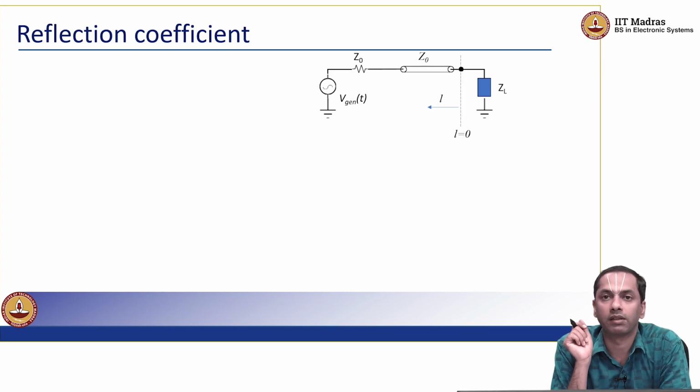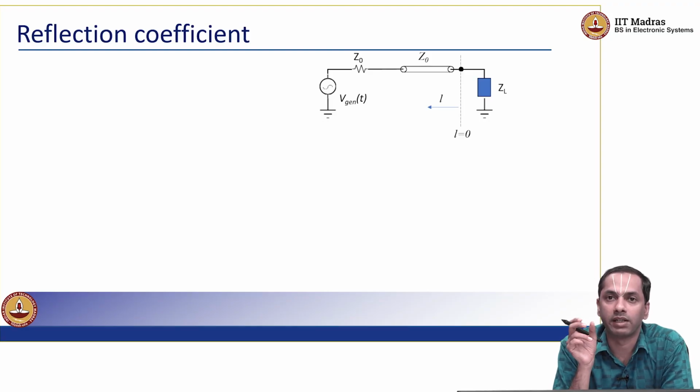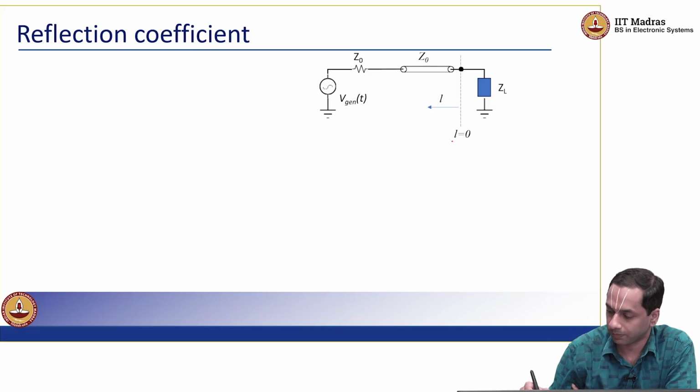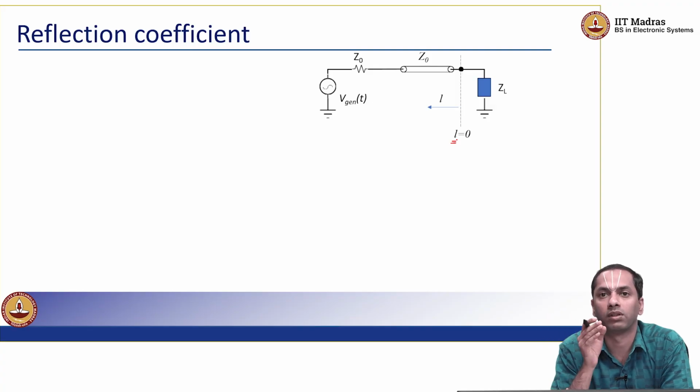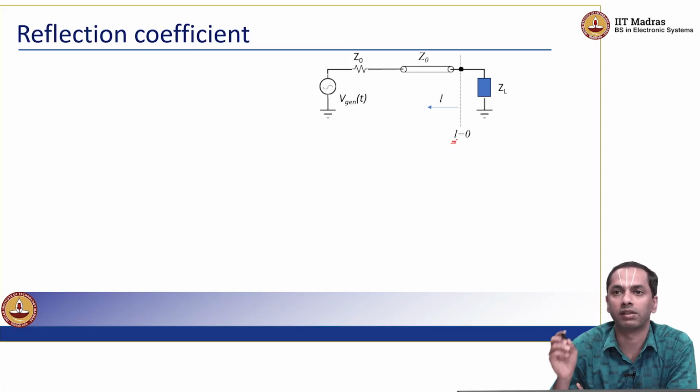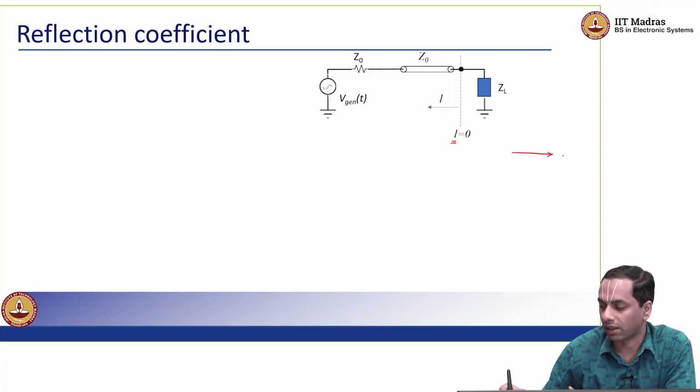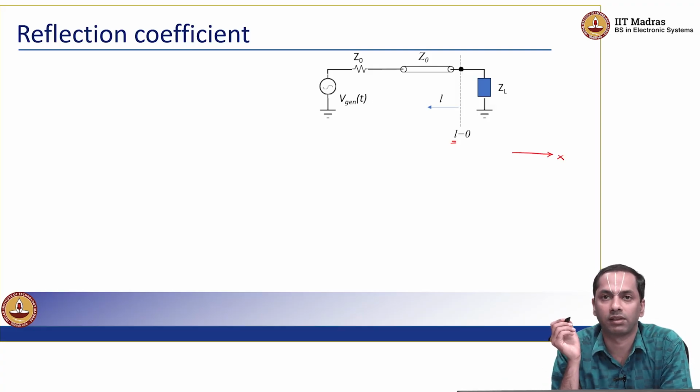So this is where I think the textbook that we are referring to, by Professor Shevgaonkar, does a small change in variable, right. So he introduces a lowercase l as the distance away from the load. Okay, so l equals 0 demarcates the location of the load itself, and as we move away from the load, l starts to increase. So remember that this was opposite to our conventional direction for x, right.